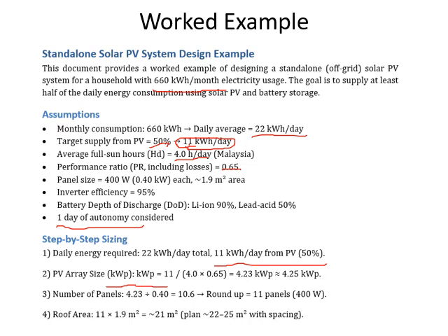So MPP is the real condition, KWP is the standard, okay, for selling. If you are telling that you're going to sell at the MPP, nobody will buy your thing, right? Because MPP is lower than the KWP.